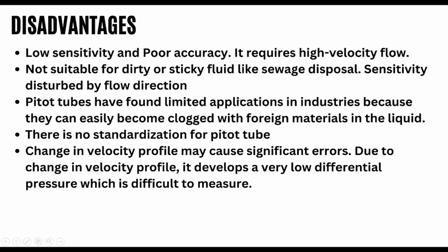And there are disadvantages too: low sensitivity and poor accuracy. Accuracy is not high. It requires high velocity of flow. It is not suitable for dirty or sticky fluid like sewage disposal. Sensitivity is disturbed by flow direction. Pitot tubes have found limited applications in industries; we don't use it in industrial applications. There is no standardization for pitot tubes. Change in velocity profile may cause significant errors. We know the velocity gradient, so there are some errors for velocity changes.